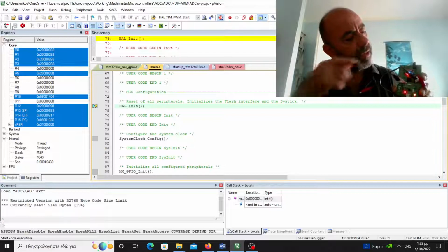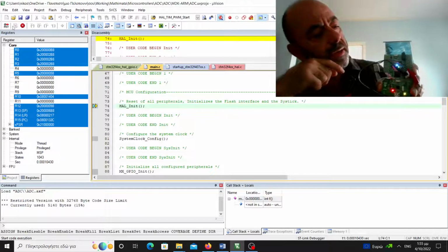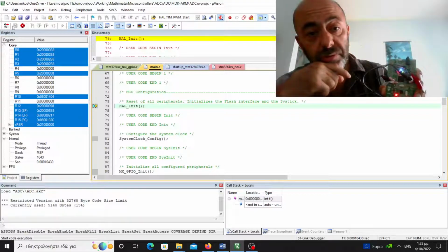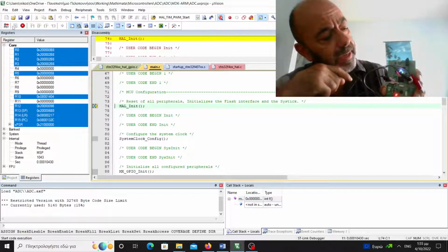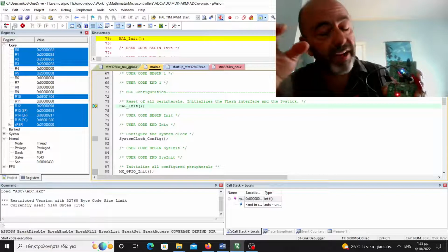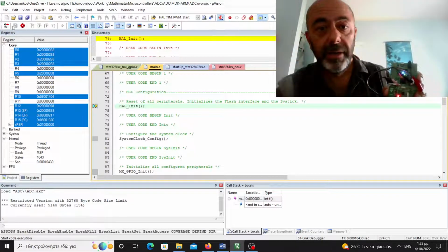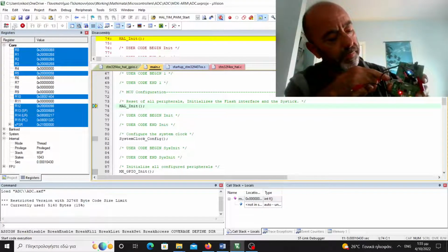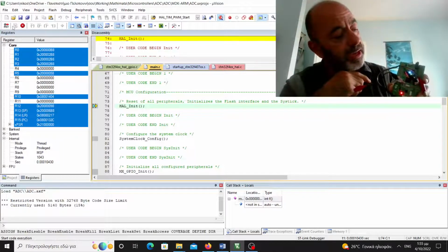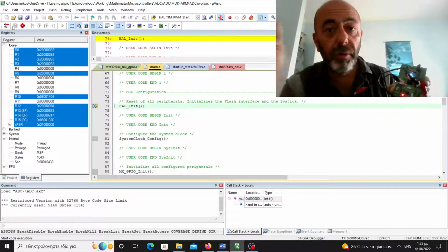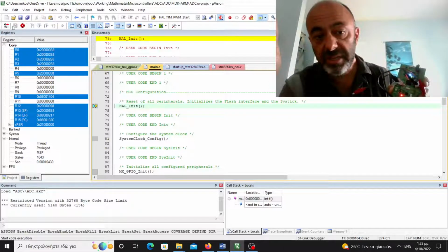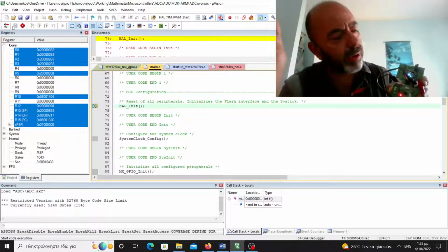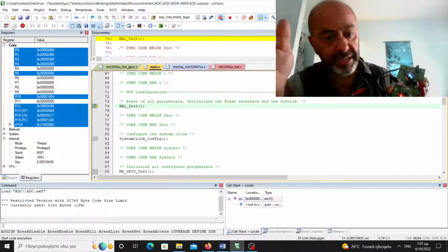And as you can see, all the 4 LEDs are turned on. This is because, as we will see later in our code, if the input value to the ADC is large enough, the more LEDs are turned on. If I disconnect the 3 volts from this point here, you will see that since no voltage is connected to the input, of course this does not mean that 0 volts ground is connected, but okay, in our case it will be recognized as 0.